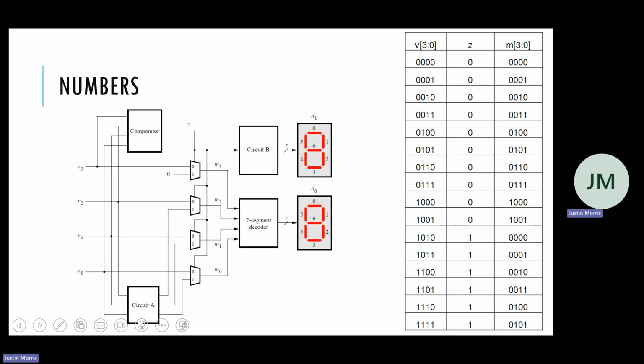So now we can move on to the lab portion of the lecture. One of the parts of your lab is being able to display multiple numbers with the display rather than just one. You have this 4-bit number, and in this case, it's unsigned, so it goes from 0 to 15. I can't display 0 through 15 with just one 7-segment display. I now need 2.